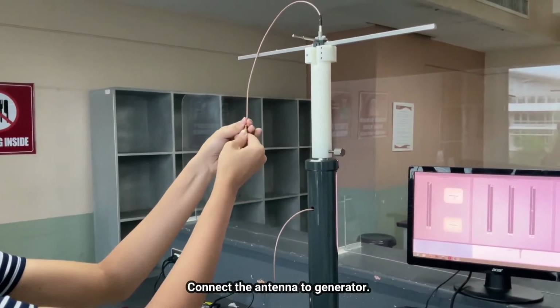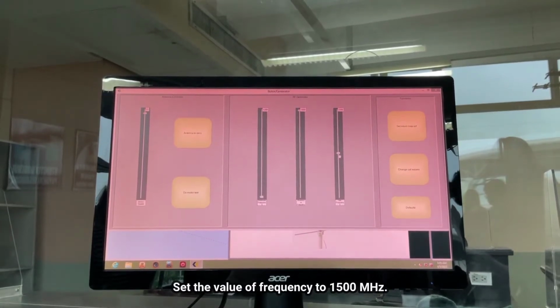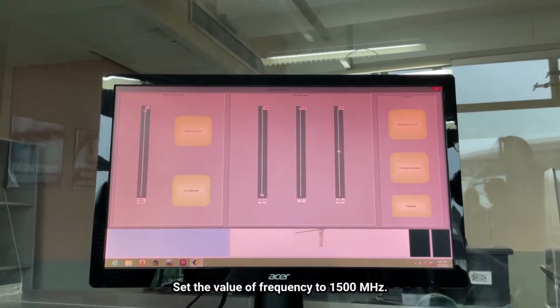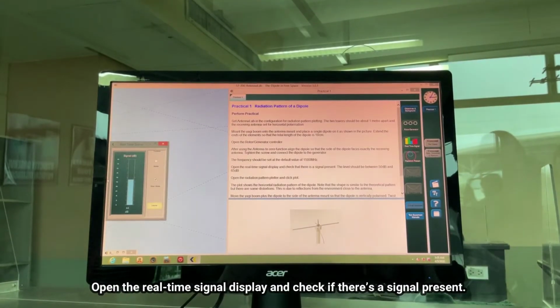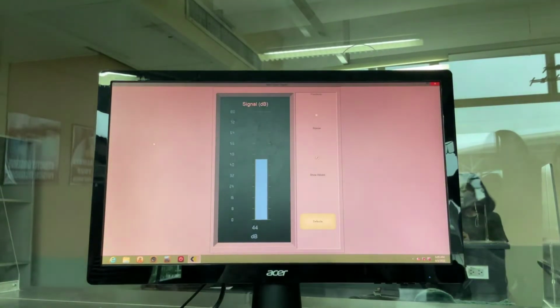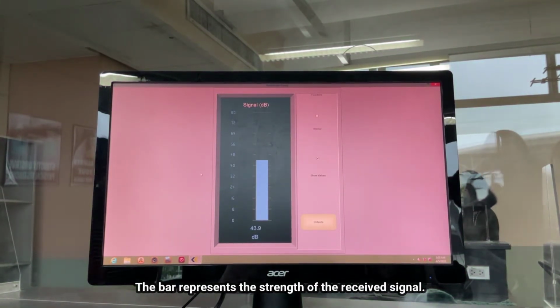Connect the antenna to generator. And then set the value of frequency to 1500 MHz. Open the real-time signal display and check if there's a signal present. The bar represents the strength of the received signal.